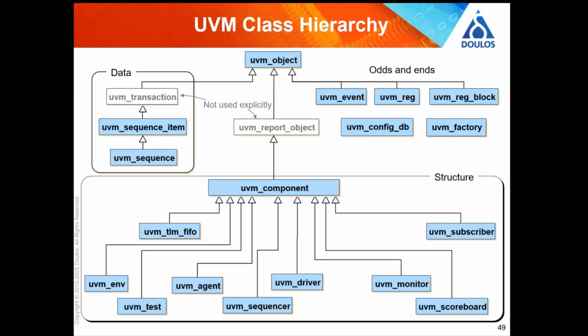You can see in the middle it says UVM component. That's the generic, what's called the base class of, you can see underneath it, it says UVM driver. You use that to make a driver. You use UVM agent to make an agent, UVM test to make a test, etc. It's test bench Lego, basically. And you can see lots of other classes for doing other things.